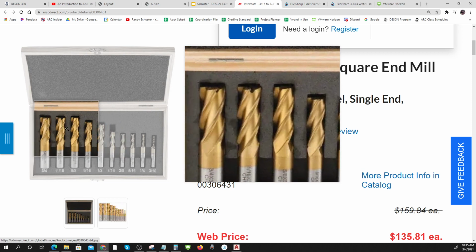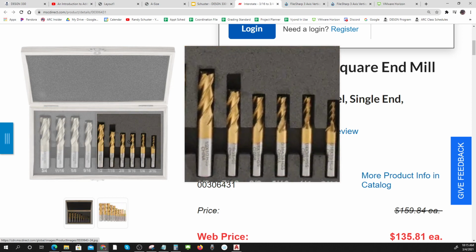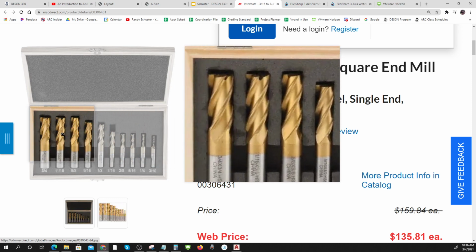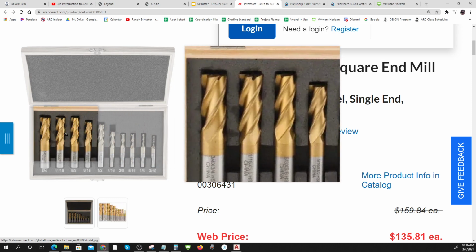That's one of the things about milling. You pretty much get a fixed diameter of your end mill. So that sets how small little corners can be and how much you can pull off. Now you can make fancy mills with different end configurations and things like that. I actually worked at a company that made lathe tool bits, form tools. So there's a lot you can do with these, but in general, it's just a cylinder that's spinning.